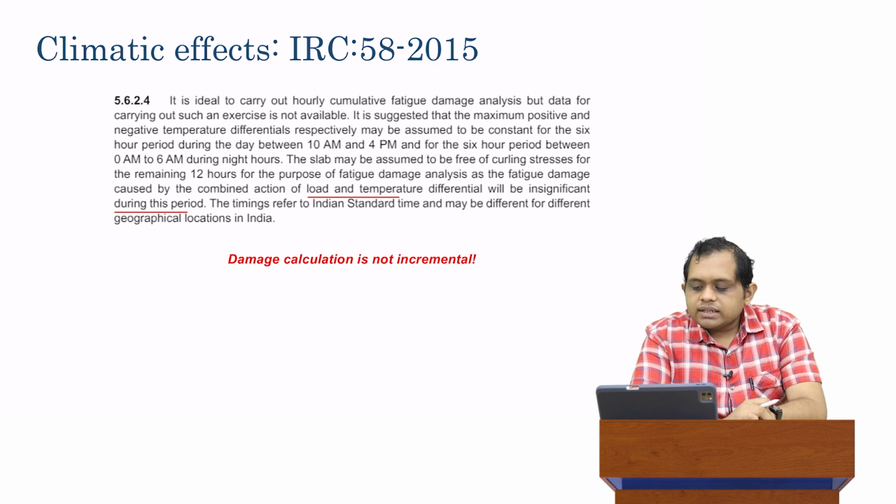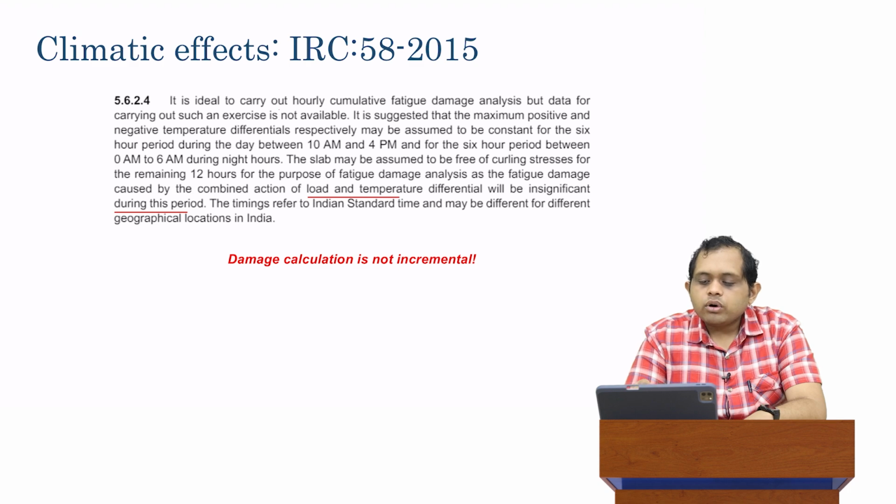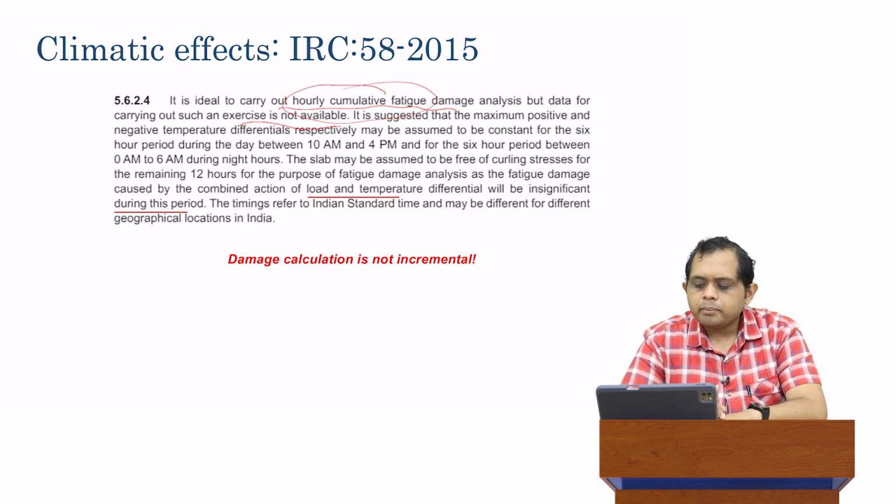Now, one other interesting observation that IRC 58 makes is as follows. They say it is ideal to carry out hourly CFD and cumulative fatigue damage analysis, but data for carrying out such an exercise is not available. So they do recommend that hourly analysis should be done, similar to MEPDG, but they acknowledge that it's very difficult to get such an amount of data.